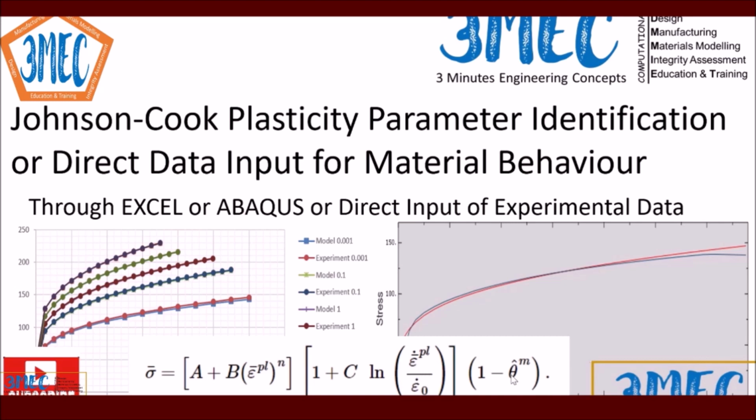But if you have stress strain curves for different strain rates, as you see here, I have 5 strain rates from 0.001 up to a strain rate of 100, and then you will have curves for different temperatures as well, so it gets more complicated, especially when you do it in Abaqus, because you will have to create a number of jobs for the individual tests, as you have done in experiments, and that can take a long time if you do it by hand or manually.